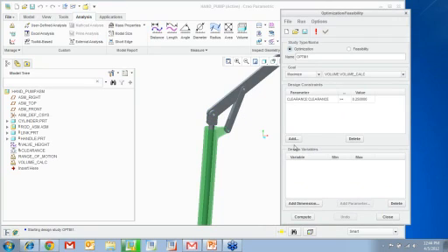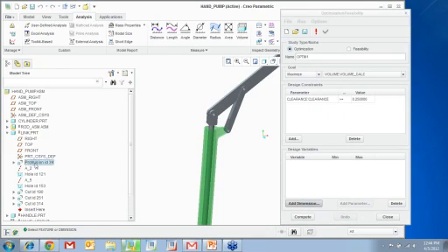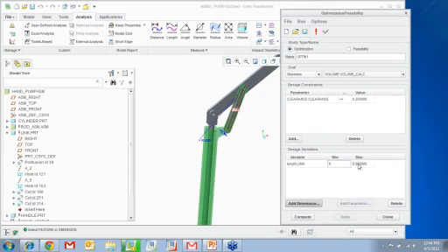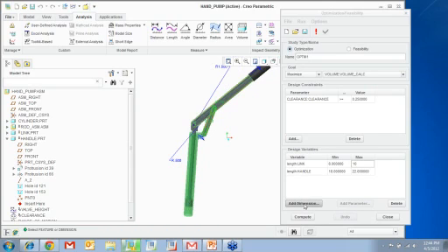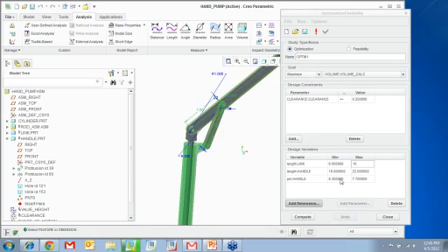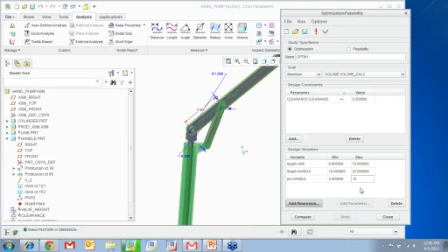So that's my clearance value, and then I go ahead and use the dimensions that I want to change. I want to change that between, say, 6 to 10. I want to change the length of the handle, the 20 dimension right there, from 18 to 22. I want to change the position of the link from, say, 5 to 10. So those are the 3 design variables that I'm trying to change. And I'm going to hit compute.